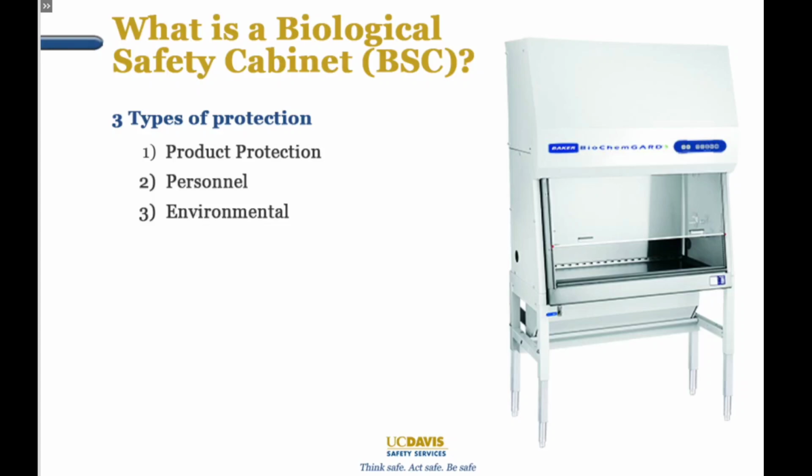Personnel and environmental protection, which means you are protected from biohazardous materials because of the inward directional air curtain at the front of the cabinet, which prevents the escape of potentially contaminated air out of the BSC prior to HEPA filtration. Of note, the air curtain draws dirty air in from the room and is immediately directed into the BSC